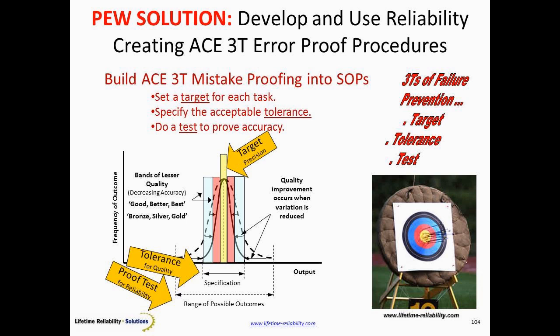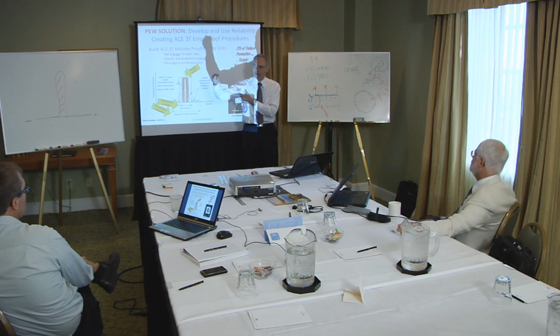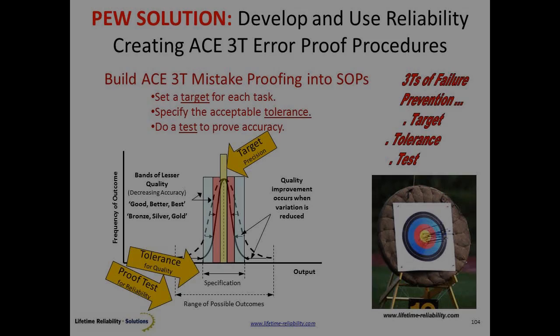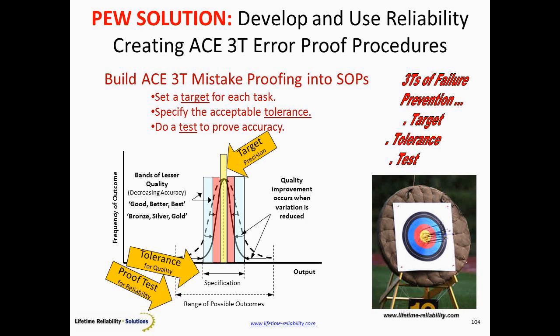What we try and do is, as the guys went through the procedure, we actually put in the tests as part of the rebuild. Because if I build a machine with 100 parts, with 200 parts, and the only test I do is at the end of the rebuild, I start the machine up and do a vibration check on the noise of the bearings. And if the test shows a high vibration within the first hour of operation, am I going to pull that machine down again and find that high vibration cause? No. I'm just going to say, oh, guess what? We've rebuilt this incorrectly, but run it anyway. I haven't got time to rebuild it. So these tests have to be done during the actual process of rebuild.